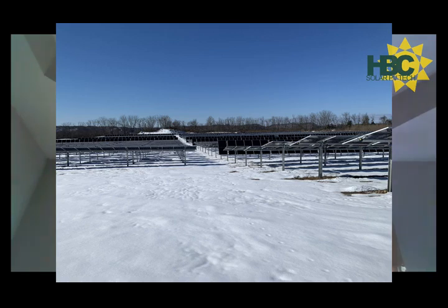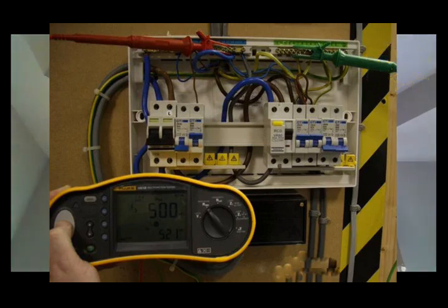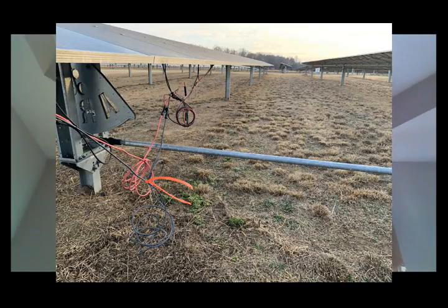In larger PV systems, you may not know which section of the array has the ground fault. One way to narrow the search is to use an insulation resistance meter, like the Fluke 1587 FC insulation multimeter or the Fluke SMFT 1000 multifunction PV tester. The meter can help you identify a subsection of the array with lower than normal ground resistance.